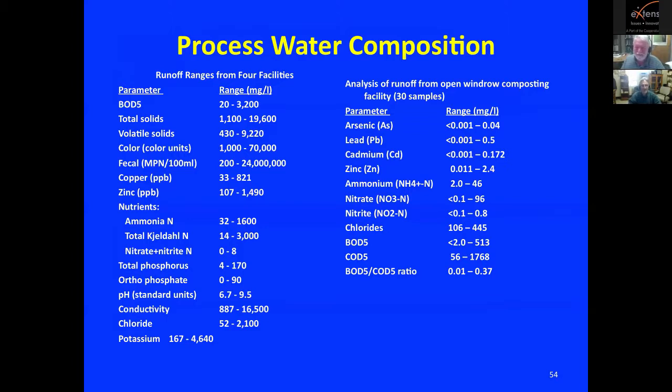So a question that came up, Gary, with all these processed water parameters is, what are some of the factors that would determine the amounts and maybe the types of these parameters you'd have in your water? Good question. There's basically two things that go into compost: feedstocks and water. And so in almost all cases, this will come from one of the two. What's in your feedstock? Well, if you're composting biosolids, you can get nutrients in there. There can be a little bit of lead in there, a little bit of copper. If you're composting something and you're using well water to do it, you can get arsenic in it. If you're composting materials that have lots of phosphorus in them, something like chicken litter, it can be pretty heavy in phosphorus. You get a lot of phosphorus in the processed water, depending on how you compost it.